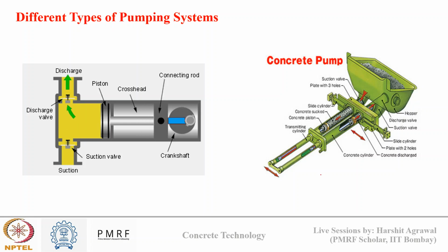Now, the type of pump used in a trailer mounted setup can be of two types. It can be a single piston or a double piston. So for a single piston, what happens? The concrete pump uses one main valve to push my concrete inside my pipeline. It is simple and cost effective.